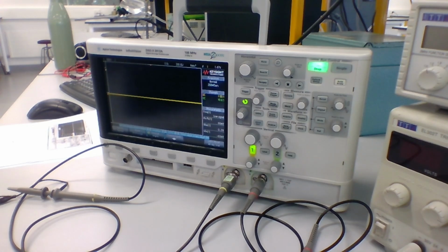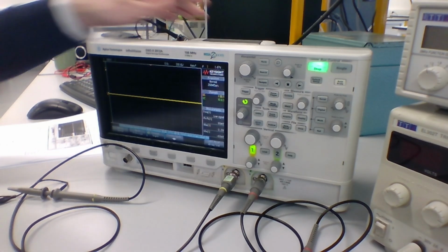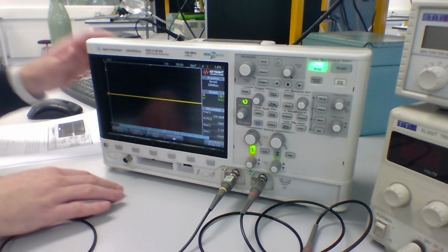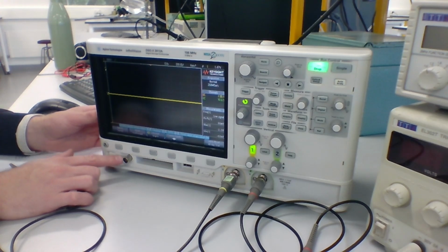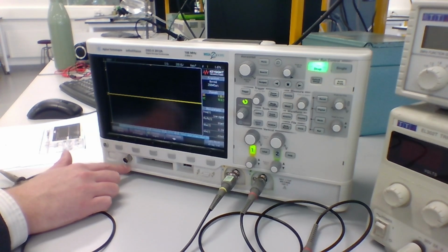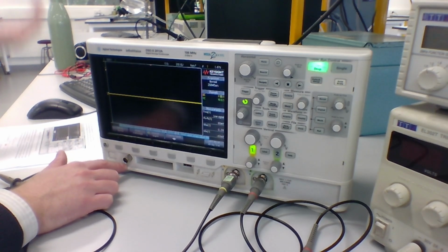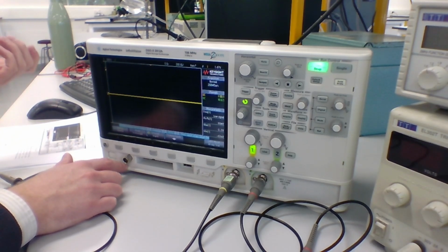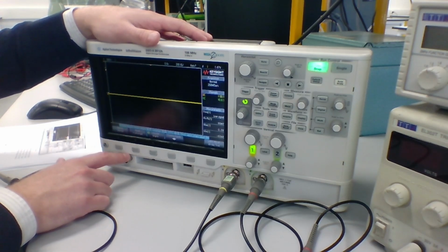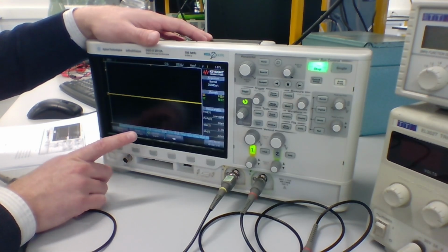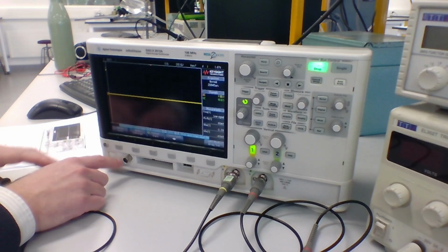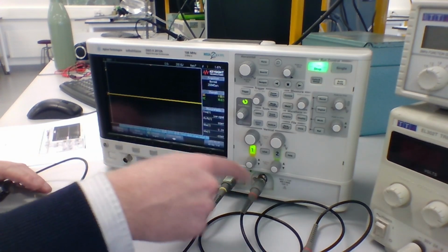Okay, so we've turned our oscilloscope on and we have connected our oscilloscope probes to our oscilloscope. Note that on the far left-hand side of the oscilloscope here, there is another connection. This has the label Gen Out underneath it. We will use this in later labs for the wave generator of the oscilloscope. If you connect an oscilloscope probe to this, you won't be able to measure anything. Similarly, you cannot supply from this using an oscilloscope probe. So don't connect oscilloscope probes to this port here. They only go in these 2 here.